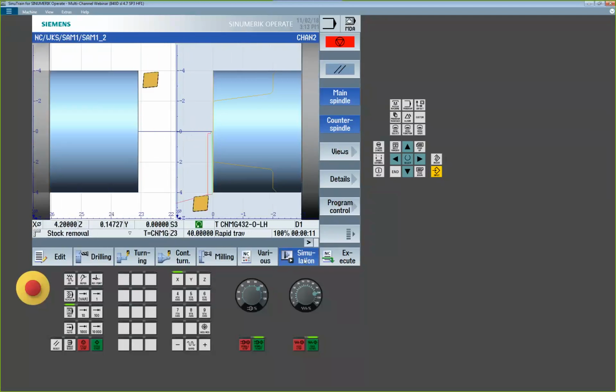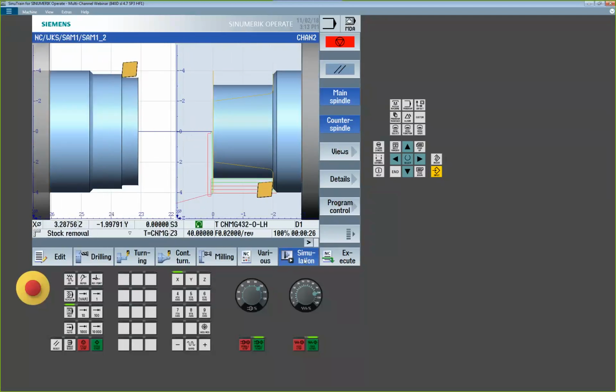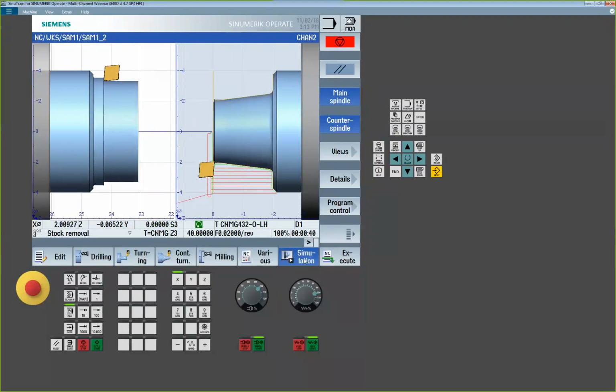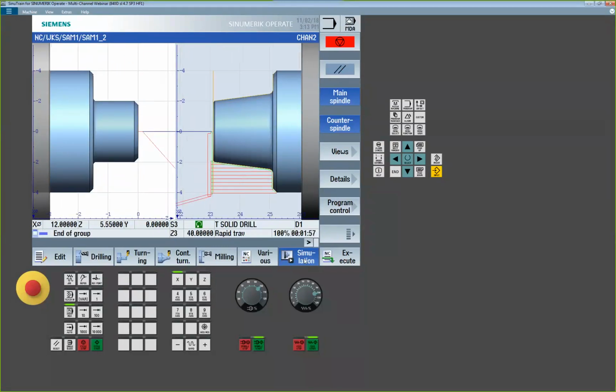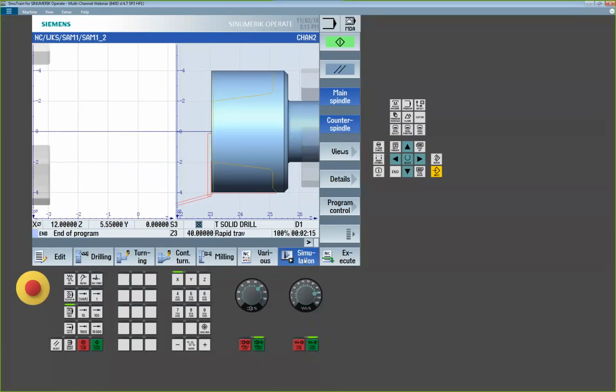So we got our turning, we have our slowed down channel 1, so we're going to have to wait for channel 1 to finish before we'll let channel 2 go over to main spindle. Then our subspindle would come over. Obviously, I would have some kind of unload process prior to the subspindle coming over, grabbing the next part. Usually that's where I would have either an automated shuttle or maybe an operator has to go in and pull the part out of the subspindle before she comes back. So there's a program stop and a command comes up. But the process, hopefully now you start to see.